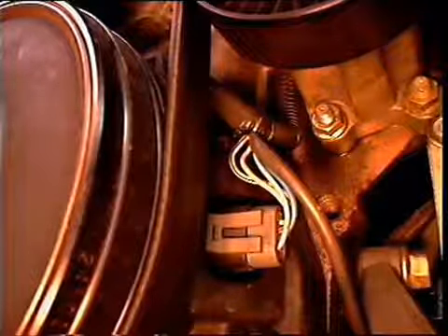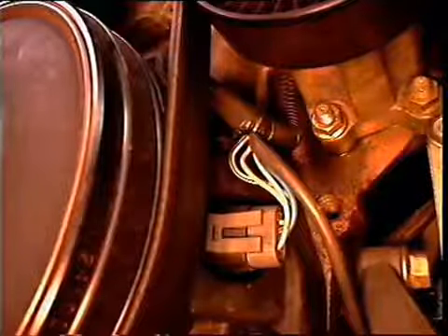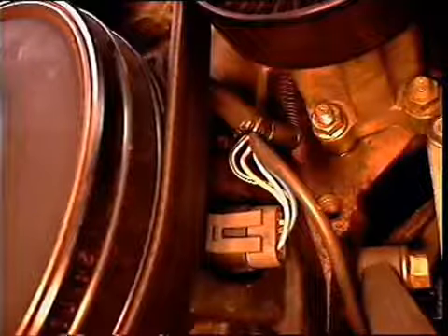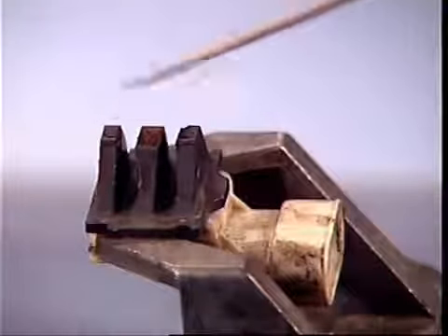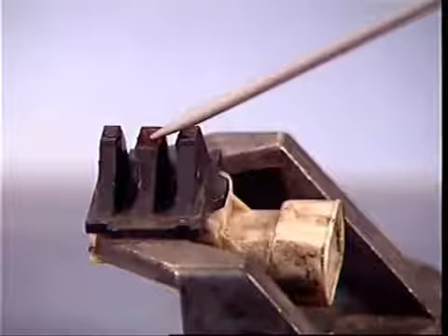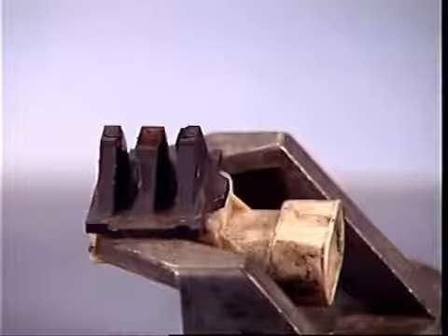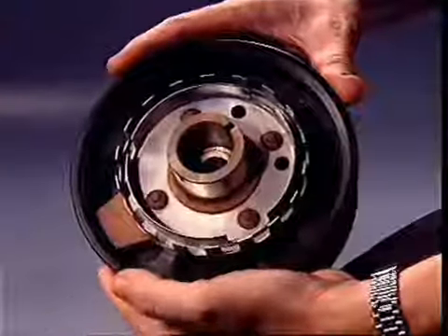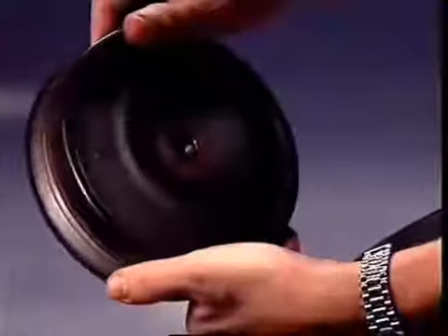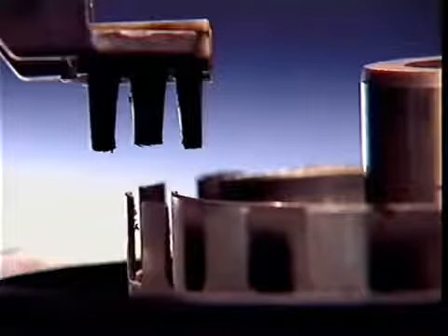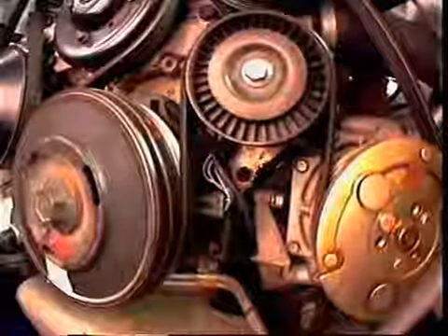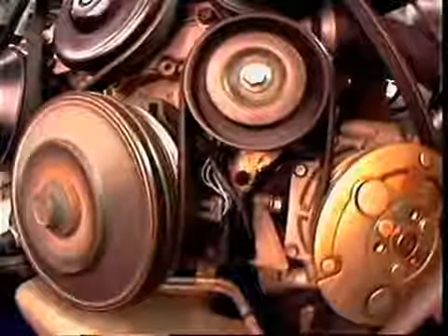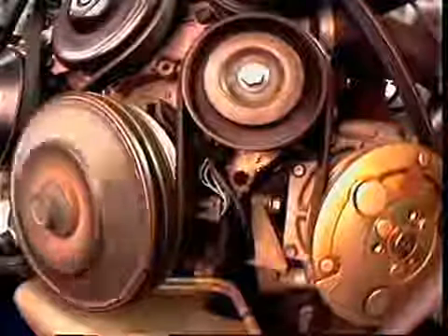Identification of each pair of cylinders and a signal for their triggering is provided by a dual crank sensor fixed to the engine timing cover. This contains 2 Hall effect switches sharing a central magnet which forms 2 air gaps between them. 2 concentric interrupter rings with a number of blades and windows and mounted on the rear of the crankshaft balancer rotate through the gaps. The voltage signals provided allow the ignition module to identify which pair of companion cylinders must be provided with ignition.